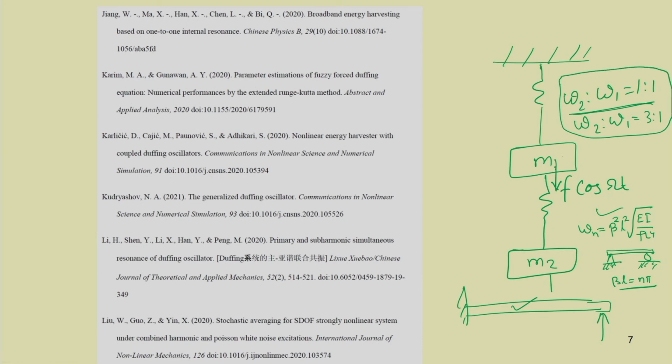Sometimes, due to interaction through the nonlinear forcing or nonlinear terms, some energy gets transferred from the excited mode to the other modes. That is why energy transfer takes place between the modes. This gives rise to a different type of resonance, and those resonance conditions are known as internal resonance conditions.